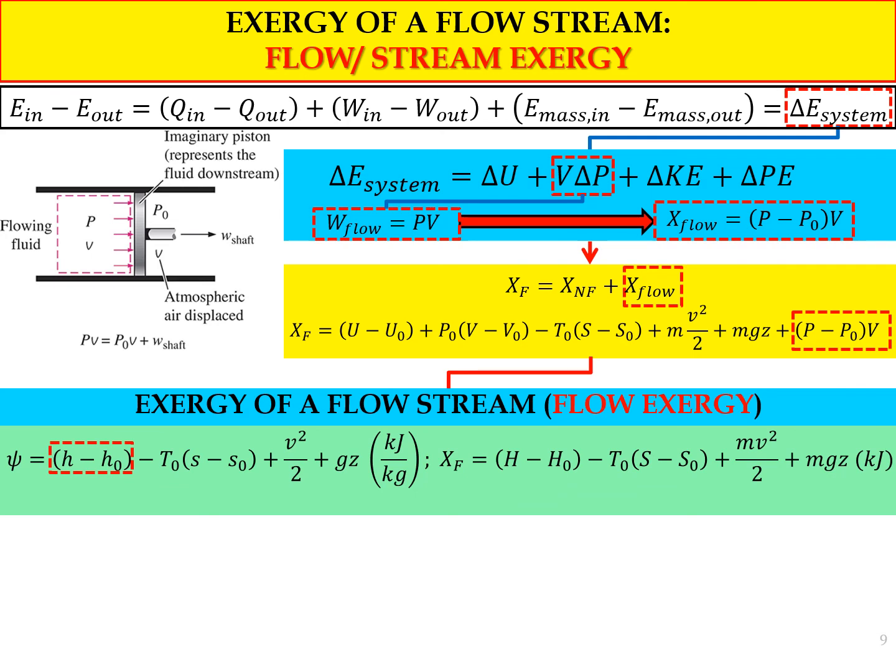However, in the flow system or open system, here is the enthalpy. How do we get this? It is from the equation that you already know from previous thermodynamics, H equal to U plus PV. From these three terms, U minus U naught plus P naught (V minus V naught) plus (P minus P naught) V, we can convert it into enthalpy.